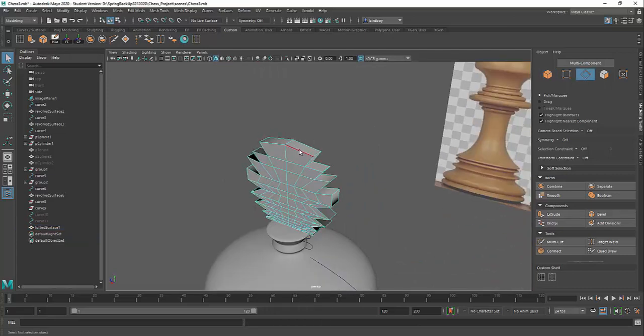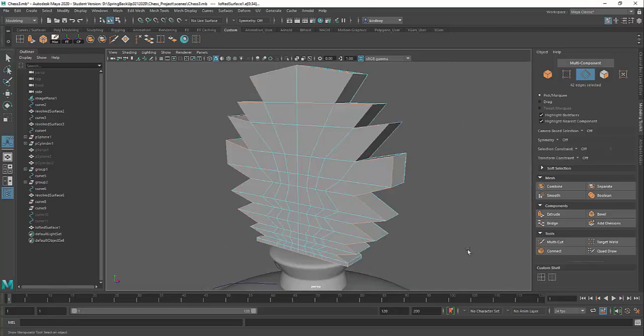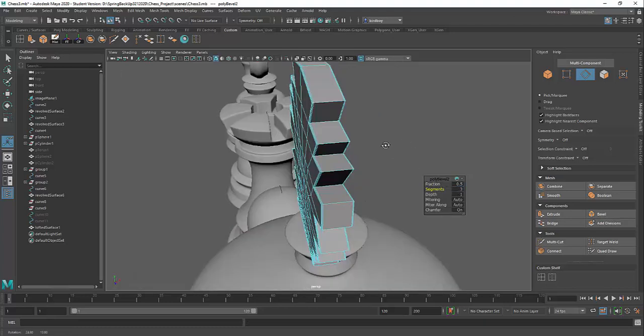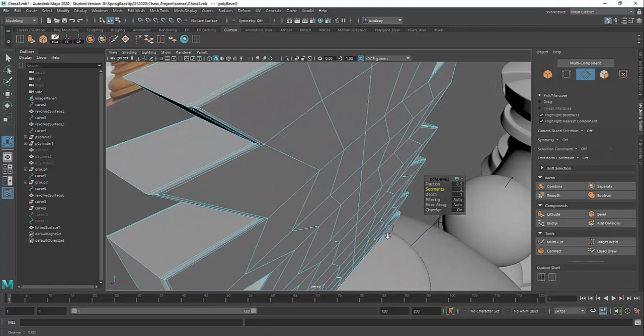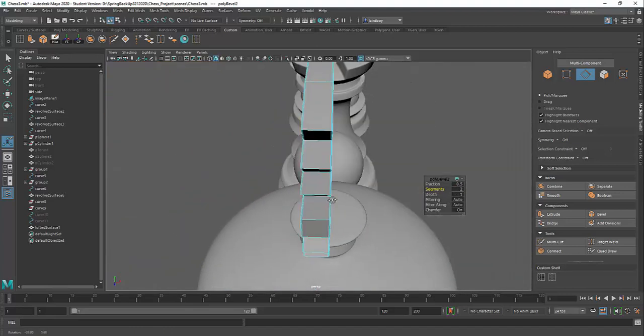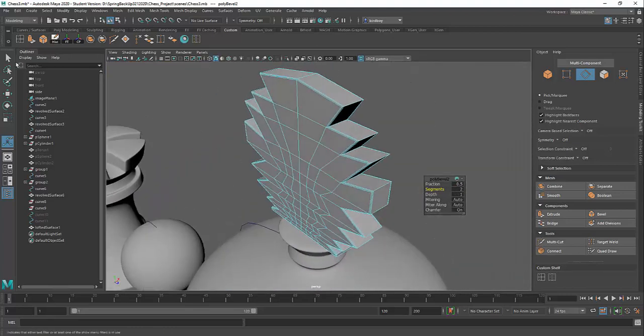Well, actually, let me just pause real quick. So I did the one side, so I'm just going to go ahead and bevel the other. I have these edges all selected. It just took a while to select them all. And I'll click on bevel. And 0.5 is good. And I think I did 3 segments, maybe 2 on the other side. Yeah, it looks like it was 2. So I'll type in 2 here. And that should be good. And then I can click out.